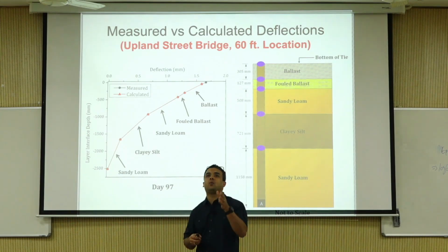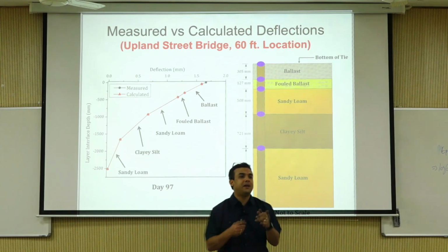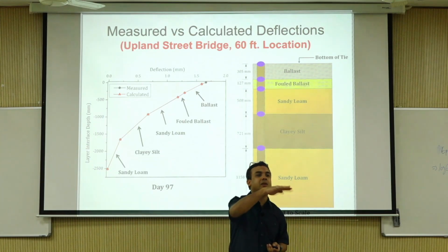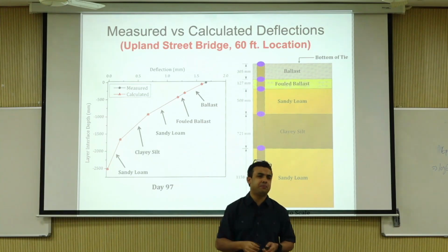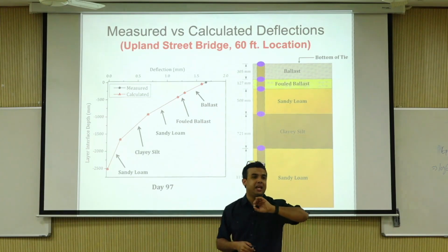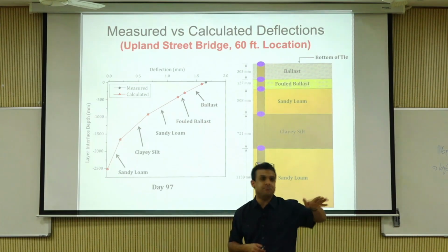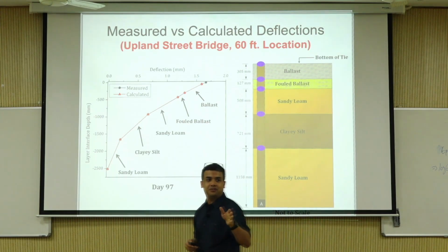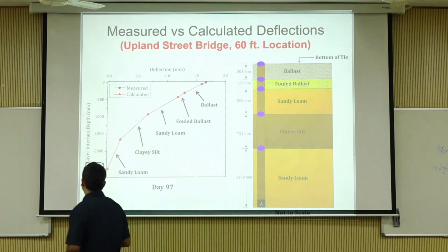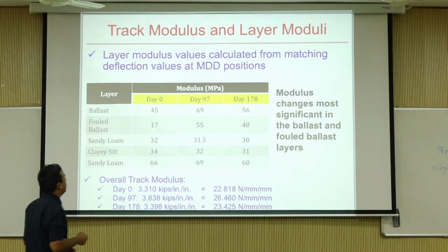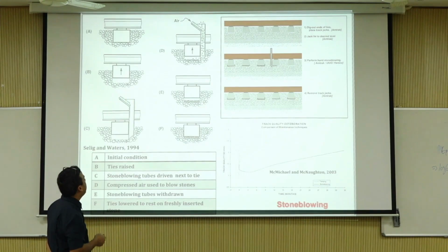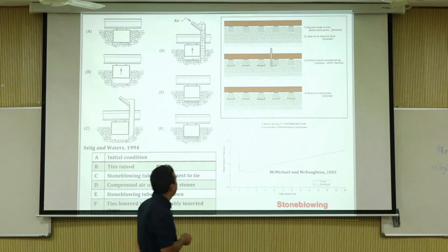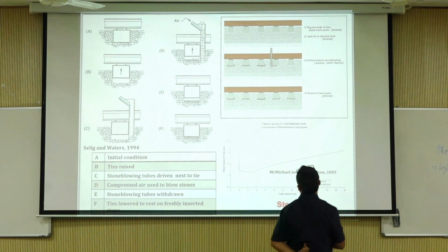They don't really quantify it as a rutting. What they quantify is called track irregularity and track surface profile differences, and there are specifications on that. But anything, even an epsilon value, is bad, because you are talking about rail, steel on steel, right? So it's a very, very sensitive subject. So how much it degrades and stuff, and then you can actually back calculate the modulus values of the layers and stuff.